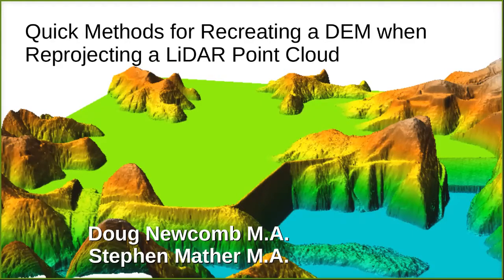So going back to the LiDAR that the DEM is created from, does it matter the quality of LiDAR, like QL2 or anything like that? What type of data did you all use? Mine was not quite QL2. I don't think the Virginia data has the vertical accuracy to meet QL2, but it had the horizontal accuracy for the point density. And I think that's the important thing, is that you need to have at least 1 point for every square, maybe more.